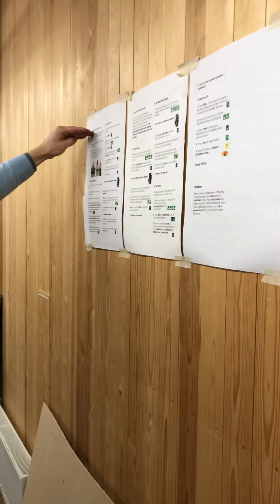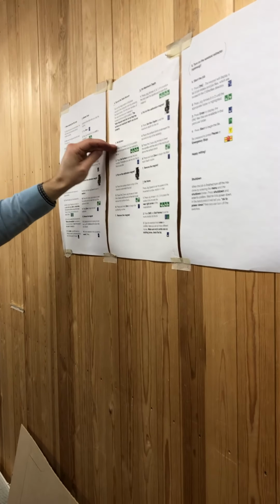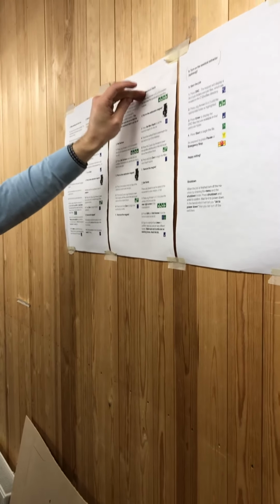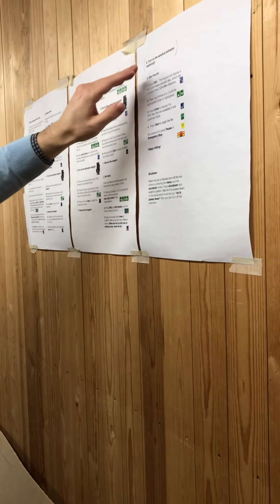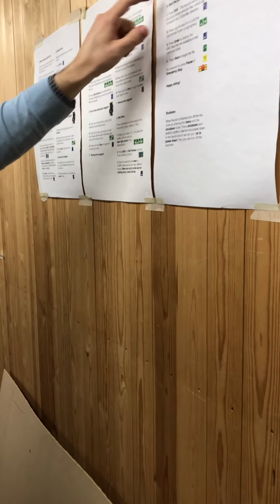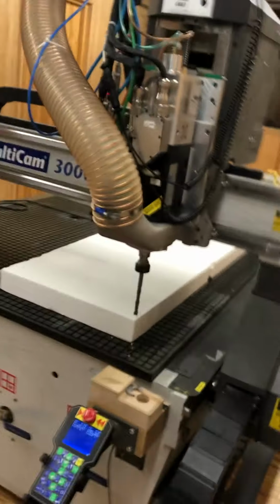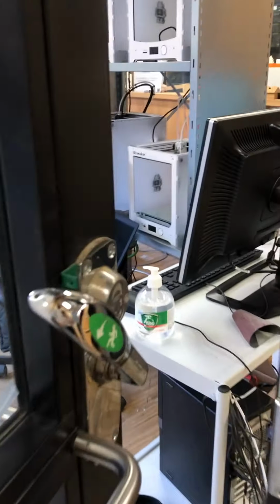So we have this here. We have started the machine, we have calibrated tools, we have turned on the table vacuum, we have set the surface, we have set the maximum depth, we have set the soft home. Alright, this one is in parentheses because it's automatic now. So you don't need to do that. Now it's start job. Double check that the magnets are here. Yeah. Alright. Because then we can go to the computer.